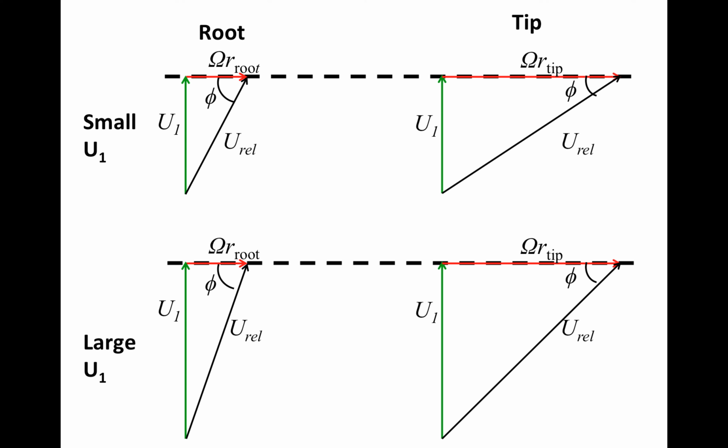It's not induced actively by turning the blades. It's just designed in such a way that when the wind speed is over the rated wind speed, larger and larger portions of the blades enter the stall regime.